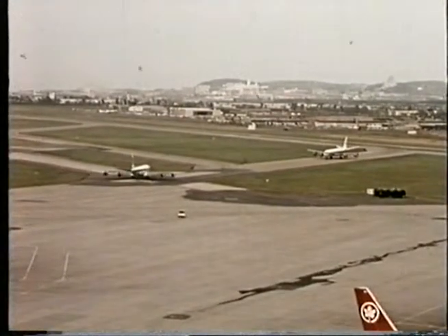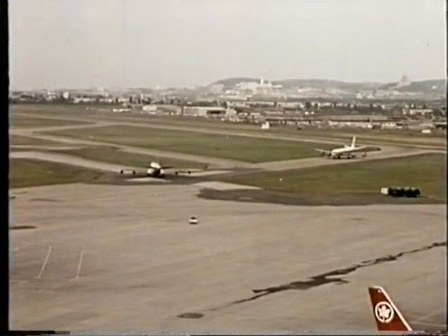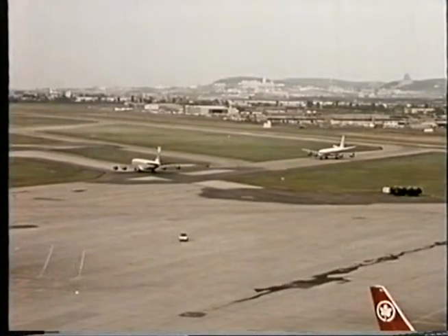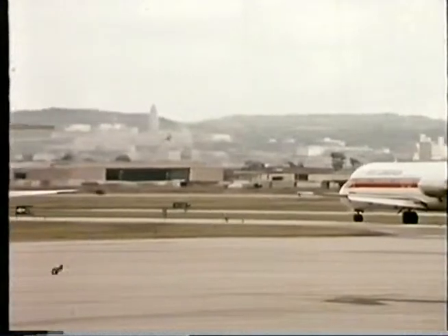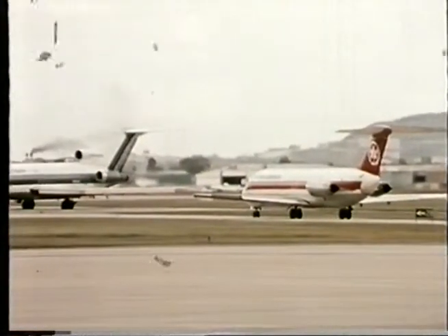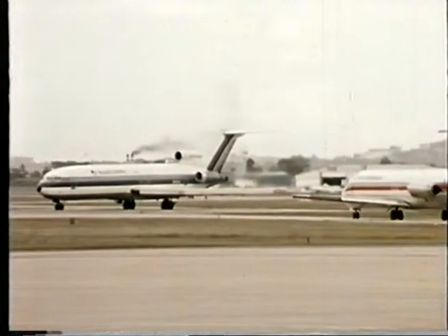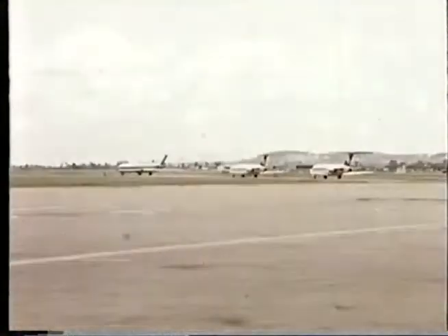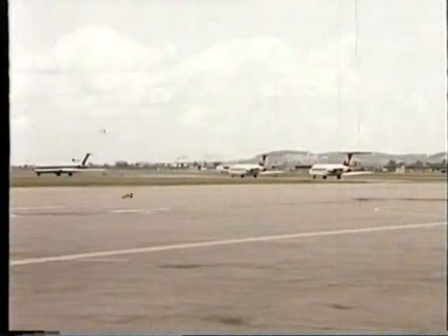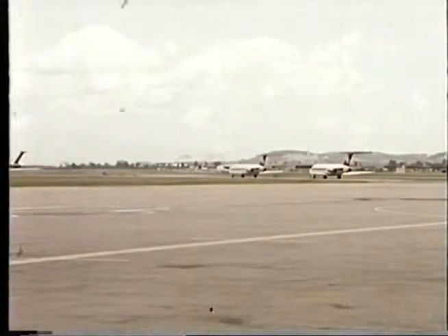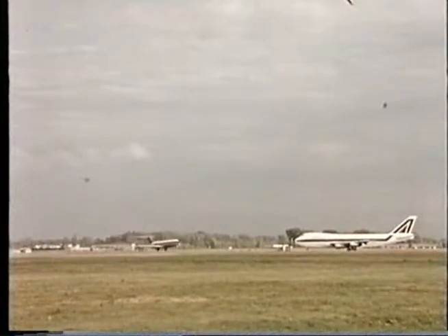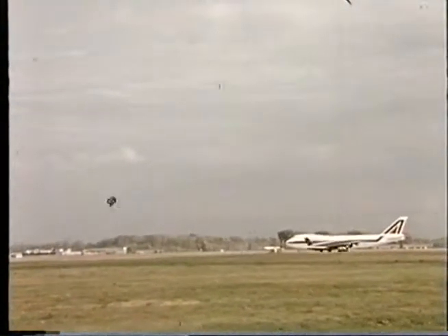Departures shall normally be cleared in the order in which they are ready for takeoff, except that deviation from that order may be made to facilitate the maximum number of departures with the least average delay. The aerodrome controller may effect separation between taxiing and landing aircraft, or in certain circumstances, aircraft taking off, by holding the taxiing aircraft in holding bays or at specified holding positions.